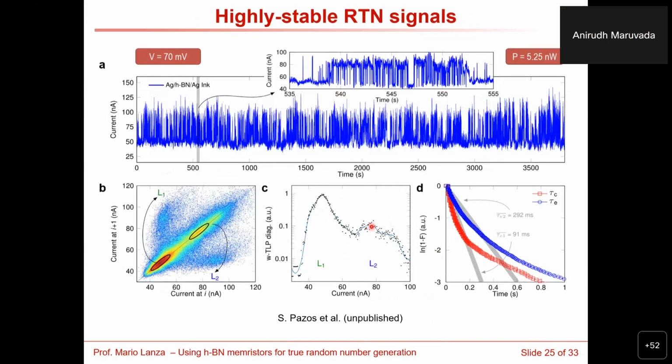Usually there is a distribution of the switching times, actually switching up and switching down, which are normally called capture time and emission time. You have this here, okay? And there is a distribution, okay? There are some cases it's very fast, some cases it's slower.